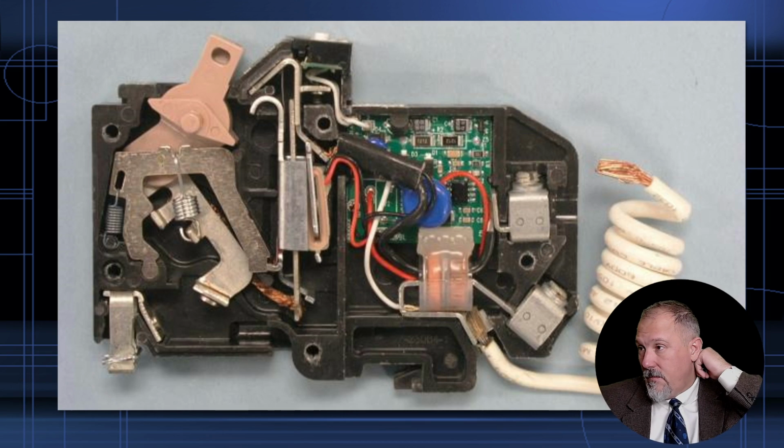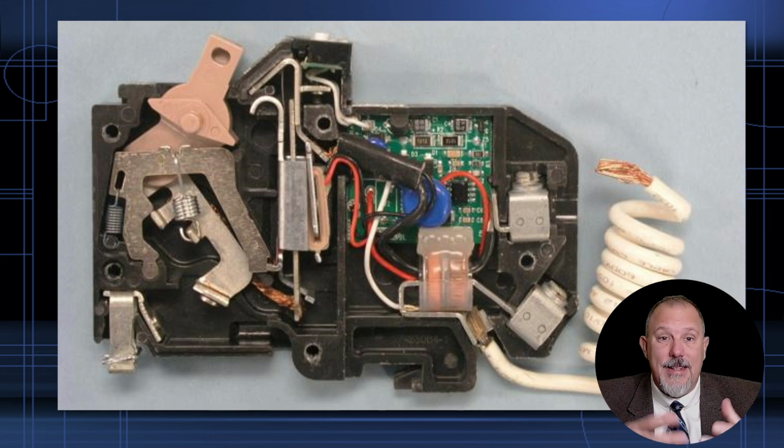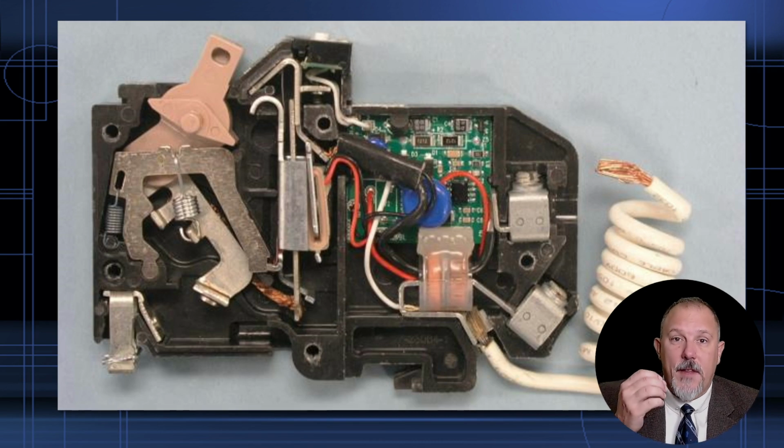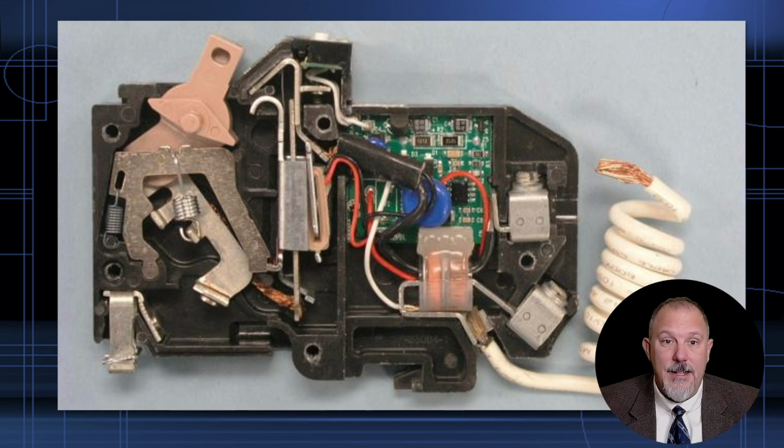One, it powers up the electronics inside the circuit breaker. I need my reference to ground so that I can power the brain on that circuit board. And two, it gives my current a path back down to the equipment grounding conductor. So that neutral pigtail has to be connected, else you have a very expensive standard thermomagnetic circuit breaker.